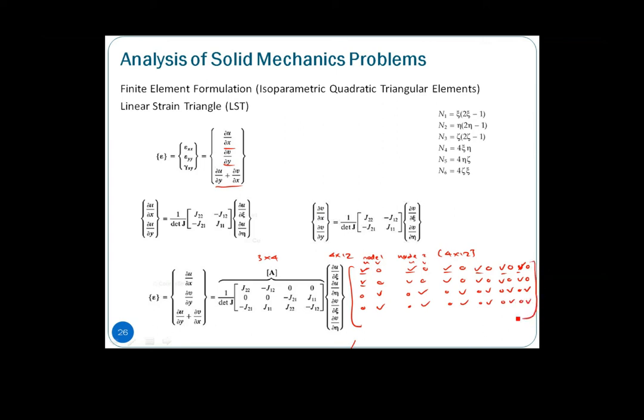Okay, so basically that gives us a 4 times 12 matrix, in terms of the full matrix, in terms of del u, the derivative of our so-called displacement field with respect to its shape, the shape functions here referring to psi and eta. So we have 4 rows and so-called 12 columns covering the 6 nodes.